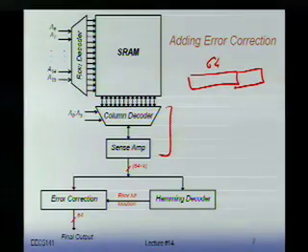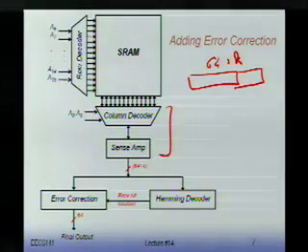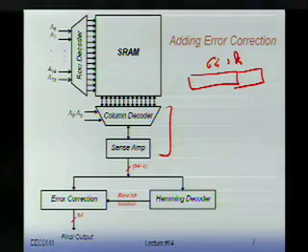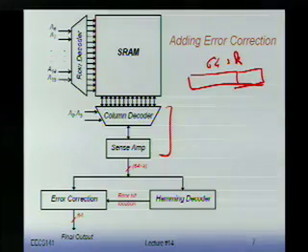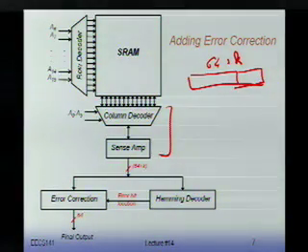If I take 64 bits, I'm not going to store 64 bits, but 64 bits plus k, where k is a given number that we're going to have to figure out. We call those parity bits. You add the number of parity bits to it. So there's redundancy, and depending upon the amount of redundancy you add, you can detect or correct a number of errors.